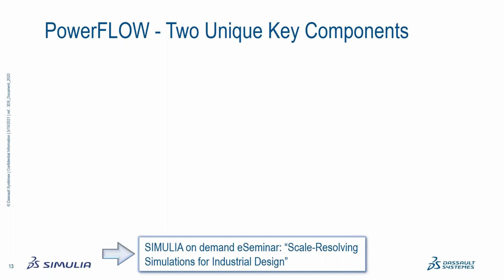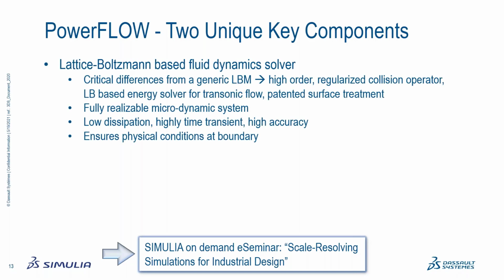Now, the PowerFlow solver, which is one of Simulia's Lattice-Boltzmann methods, has two unique components. The first one, as I mentioned earlier in the summary, is that we have a Lattice-Boltzmann-based fluid dynamics solver, which has critical differences from a generic LBM. As I said, we have a high order method, a regularized collision operator, and we're using a Lattice-Boltzmann-based energy solver for transonic flows and a patented surface treatment. This describes a fully realizable microdynamic system with low dissipation, which is highly time transient and highly accurate, and we can ensure physical boundary conditions.